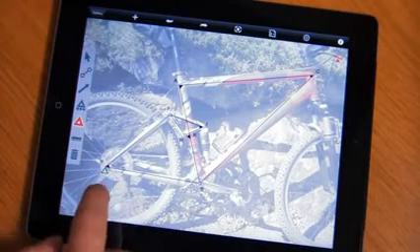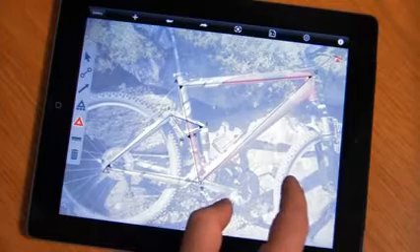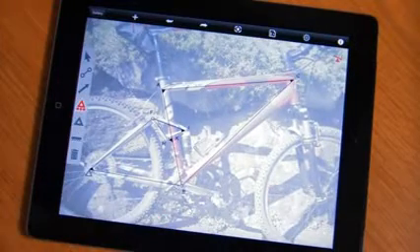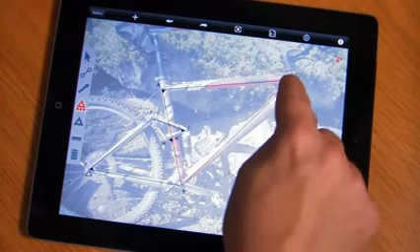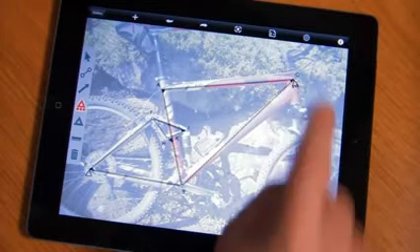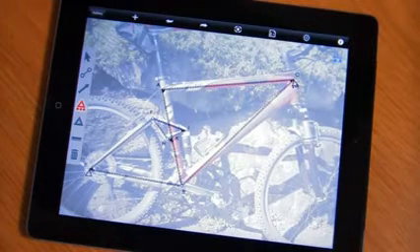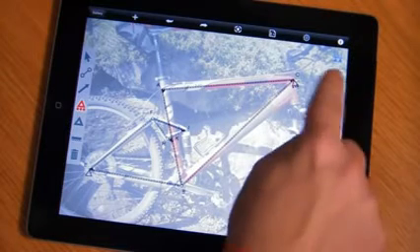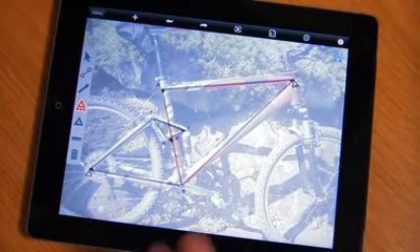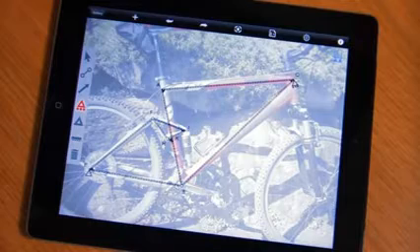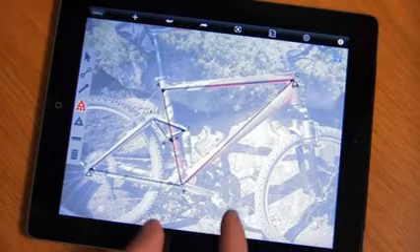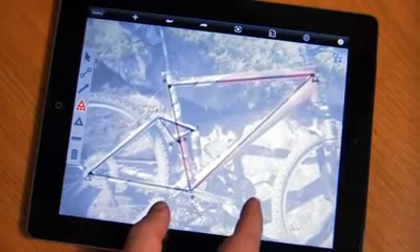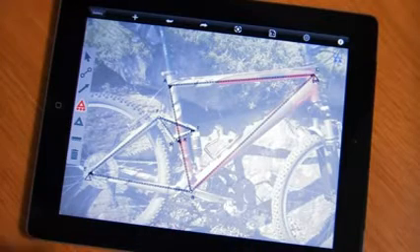We'll start out by adding a pivot support to the back of the E. And then we're going to use a sliding support to represent the forks at the front end of the bike frame. We'll try to align that with the forks so our reaction forces are proper. Now notice the system is telling us we've got an over-constrained problem. That's because we have a fairly complex layout here. We've got multiple systems here that we're trying to analyze, and that's perfectly okay. ForceEffect will handle this just fine.